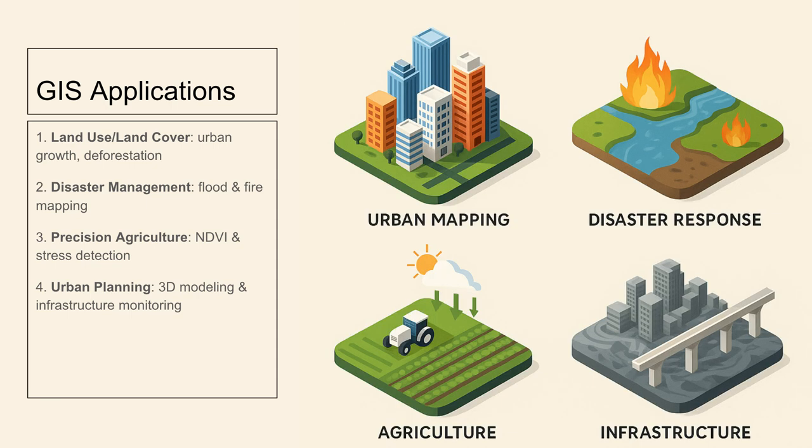The integration of remote sensing data into geographic information systems is essential for monitoring land use and land cover changes across spatial and temporal scales. Remote sensing supports disaster management at all stages, from early warning to response and recovery. GIS platforms integrate remotely sensed data, optical, radar, and thermal, with ancillary spatial data such as topography, infrastructure, and population density to inform decision-making. Remote sensing provides critical data for agriculture, including crop health, growth stages, and yield forecasting.